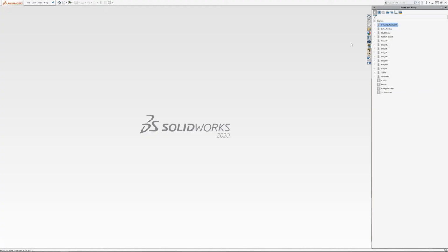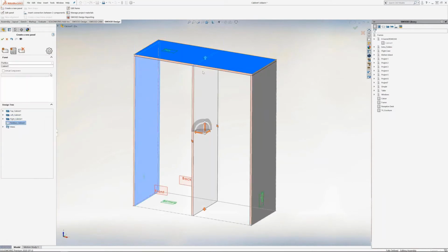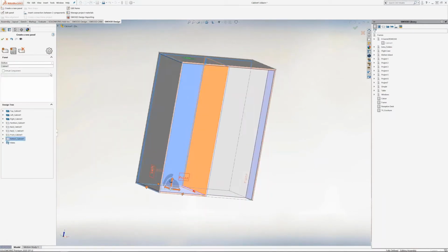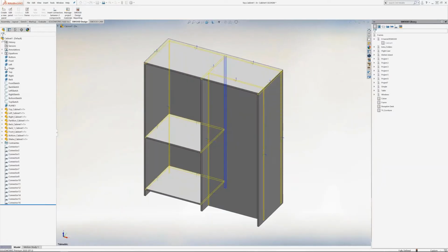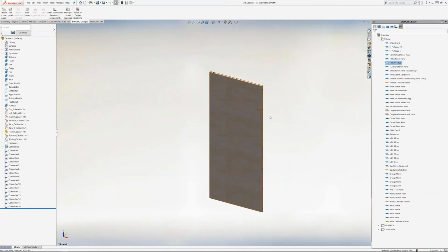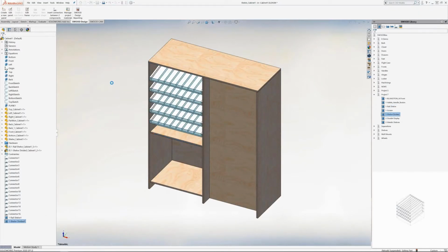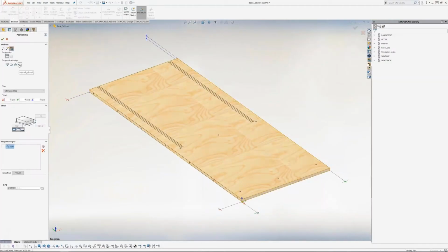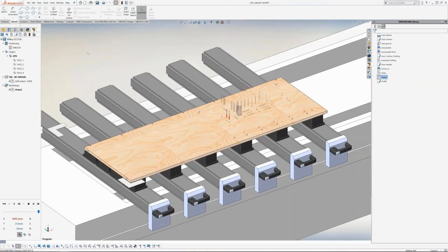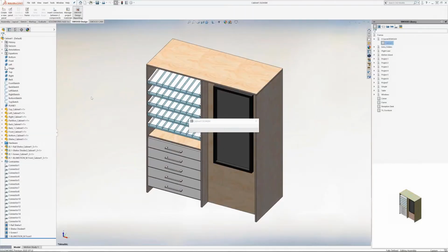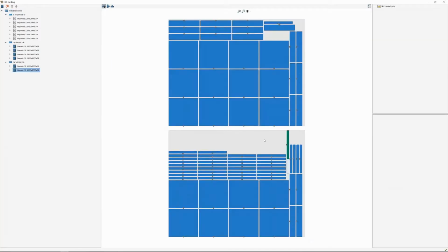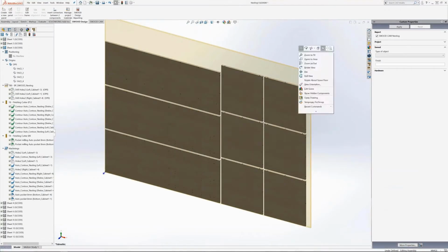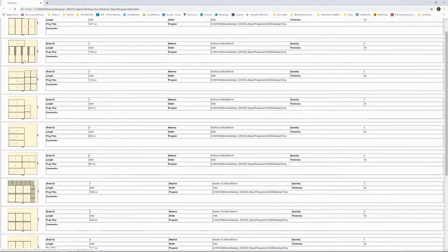We'll see that in a very short video that I have accelerated here. Here you have the main functions of SWOOD Design first: how to create a frame, the carcass. Then how to add connectors between those panels with the SWOOD features. Then you can see the material management, how to change material, apply edge bands and so on. Now we are adding some components using SWOOD Boxes. Here you can see SWOOD CAM, where you can create the program easily. Now we'll see very quickly the reports, all the documents that are created automatically. And finally, the nesting results from the project that we have seen before.